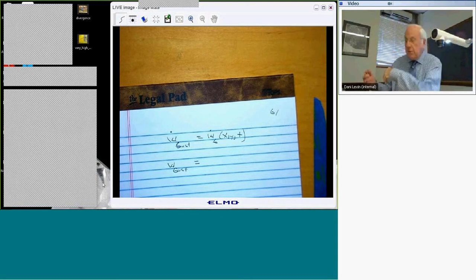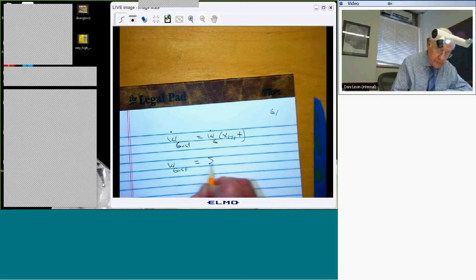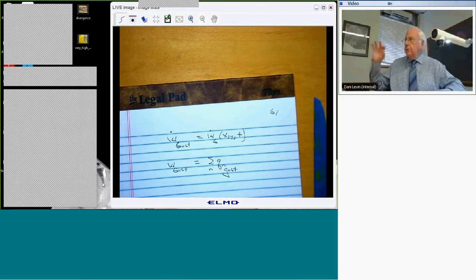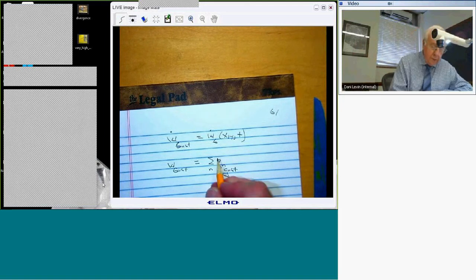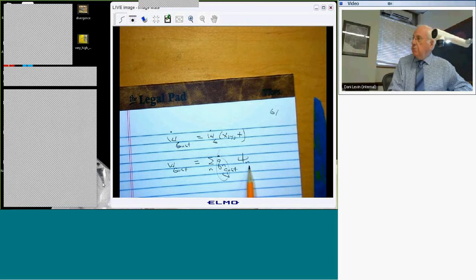So I could write this as Qn sub gust. These are not the Q's associated with structural motion. This is just a representation of the gust velocity field. If you want, I'll put a dot over here to indicate I'm talking about velocity. I could do this. That might be interesting because looking at the coefficients of this representation, that would tell me which modes in the structure are most likely to be excited by that gust. Did I tell you what you wanted to know, or more than you wanted?